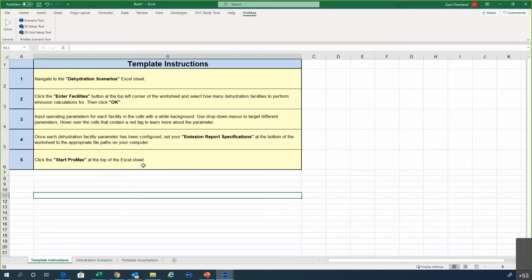That's a good point. Cynthia mentioned that in addition, the flare controls up to 98%. So you have 2% of those vented to the atmosphere. So even if you do have a flare present, we can't assume that it's going to combust 100% of the hydrocarbons. So that's a good point.